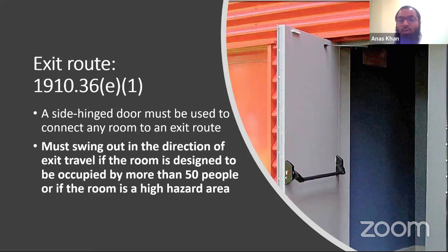Side hinge door, which can be opened from inside, as required by our local Saudi authority. It is a mandatory requirement now for the emergency exit. You need to install these kinds of doors whenever you have 50 or more employees, so that the door can always be opened from inside.